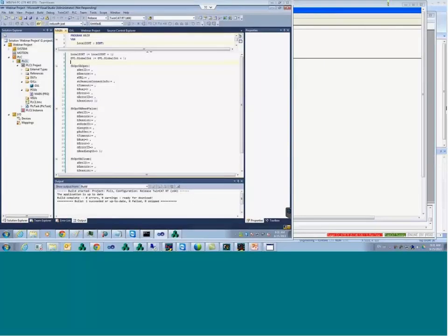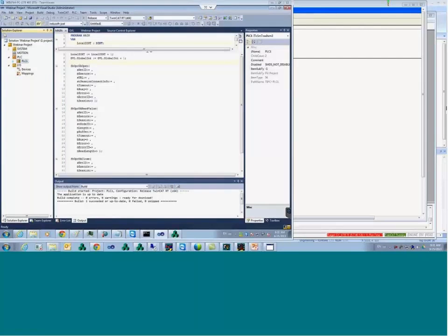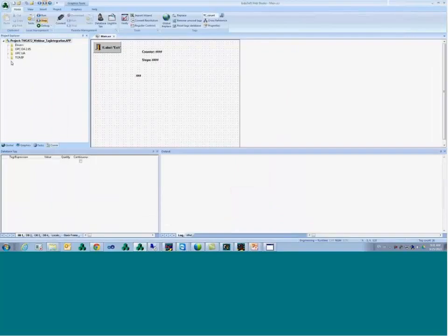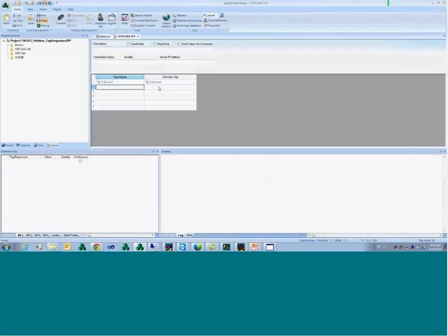So I got a question here, very interesting. Is the communication between two InduSoft sessions via TCP/IP worksheet faster than configuring a driver sheet to access the tag directly on the PLC? By TCP/IP communication, he's probably saying our TCP/IP task, where I can insert a worksheet and put an IP address from another InduSoft application. And here I'm going to have my local tags and my remote tags from the remote application.